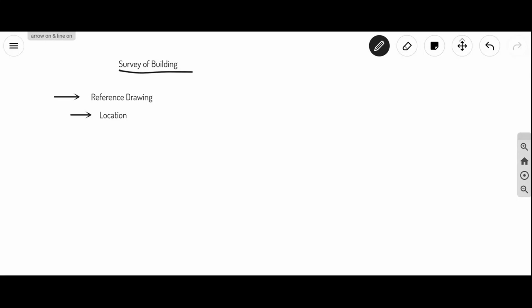Sometimes the client will give a project from India itself, but the project location will be in Dubai. So in the drawing, at one corner, they'll specify the location of the project. Check that location. If that location is not there, identify the location from the client or architect. From the contact person, you take a written approval that this building is located in this location. Hope I am clear, right?